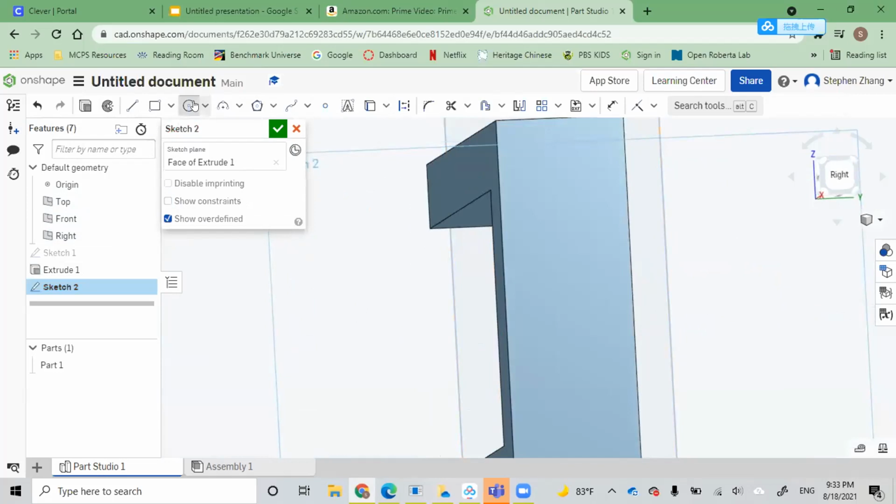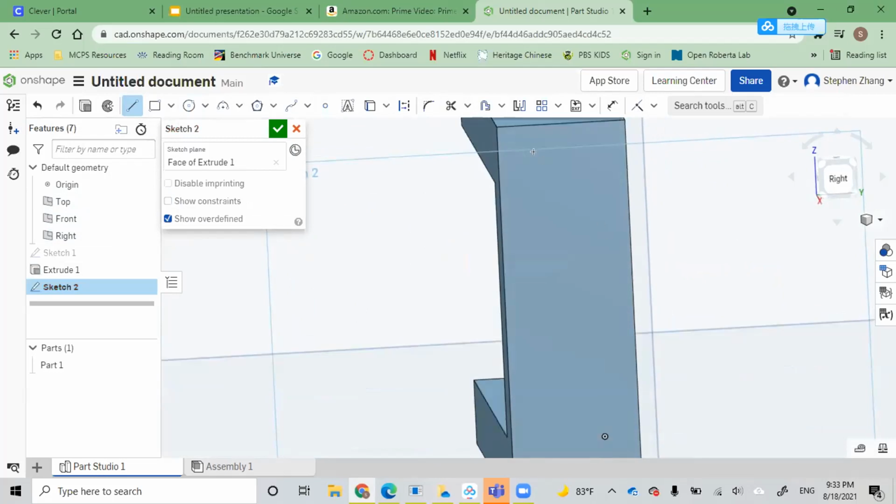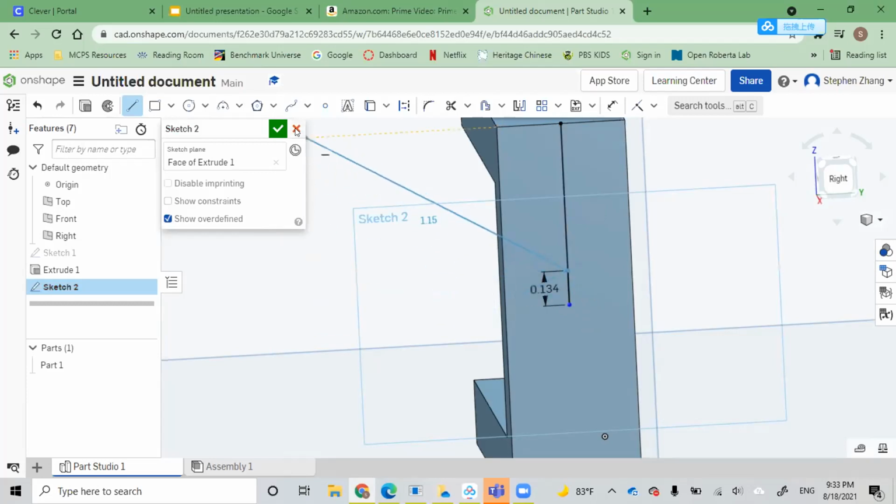What you can do, try to make a line using the line tool. Yep. We're gonna make our construction line. Okay, and so if you hover. Is this a line, or am I supposed to make something else? Yeah, hover there, and then just connect it to the other end. Do one for the other direction, so it's running side to side. And that'll allow you to obtain the center point of that rectangle.